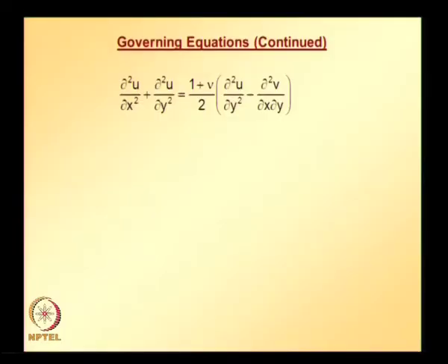second order differential equation starting with the equilibrium equation in the x direction, substituting stresses in terms of strains using the stress strain relation, and then substituting strains in terms of displacements using strain displacement relations. After a couple of mathematical manipulations, we finally arrived at this equation.